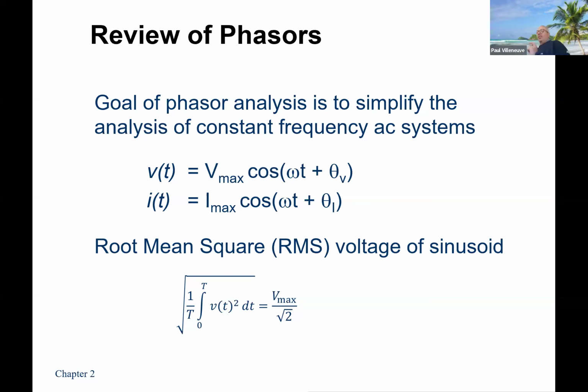So we're going to start off this class by looking at our two waveforms, voltage and current, and we're going to write them as having a magnitude and an angle. And the angle is not the phasor angle that we're talking about. It's actually the angle because there's potentially a phase shift. We started to talk a little bit about ELI the ICE man yesterday and how we had a current or a voltage present before the other term. So we can do that here by adding in a phase shift. So we don't have to have a pure sine wave or a cosine wave that starts at 0. We can actually start at different times.